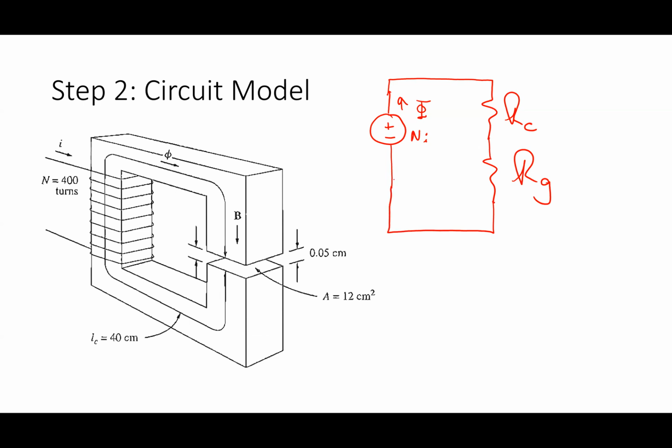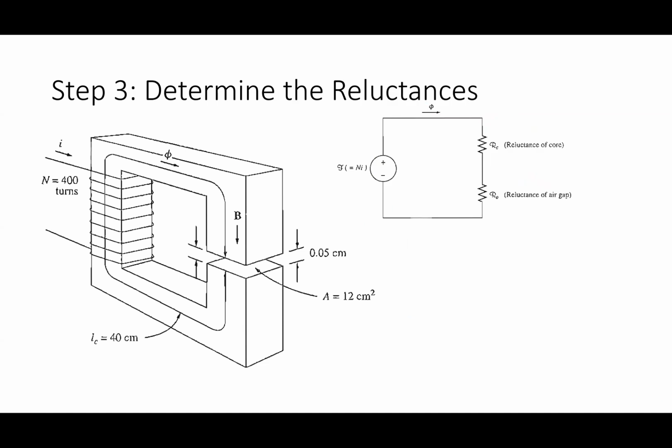Now, why don't I just have one? Why are they different? Different permeabilities, right? What's the permeability of the gap? It's air, so it's mu naught, whereas this one is, I said, just mu. There are two different materials. Now notice, in this problem, that means I have to define what RC and RG are. So RC is this character right here. So what would RC be?